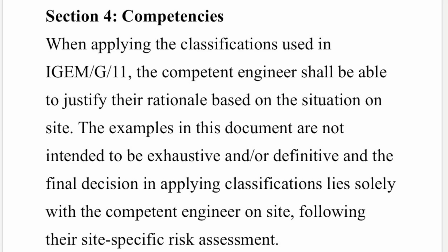So the whole thing about the unsafe situations procedure is, an engineer going out to service, repair or install an appliance finds an unsafe situation, and it's up to that engineer to make the decision on whether they think it's at risk, ID, not to current standards, and whether they need to RIDDOR it or not. So it's your decision, and if you decide that situation is at risk, then you need some evidence to back it up to make sure that you are categorising them correctly.